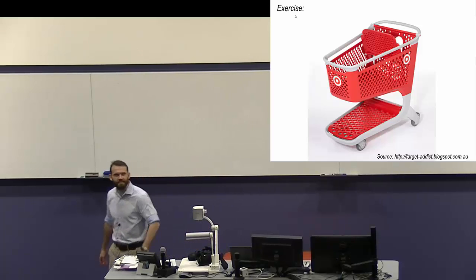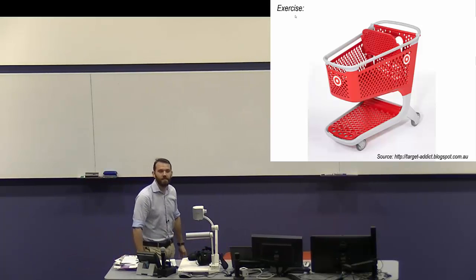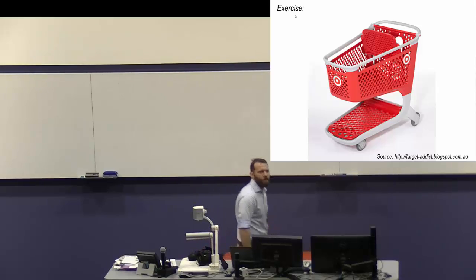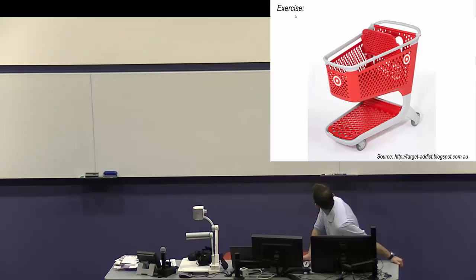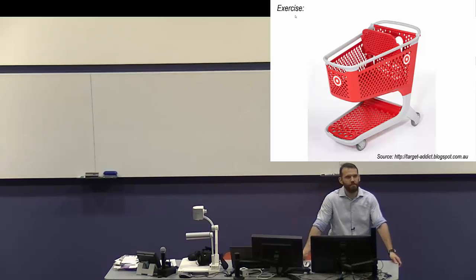Any other positives? A light material, yeah. Now, depending on what the material actually is, could it be cheaper than steel, maybe? Probably. So you might be able to mould this rather than weld it, and so it might be cheaper to manufacture, might be an advantage. Any other pros for this design?